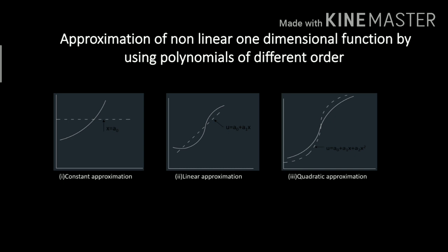But in the case of the third figure, as the polynomial selected for the formulation of the shape function is almost correct, the geometry of the two curves is nearly the same. From that, we can infer that a suitable polynomial is to be selected for the formulation of the shape function. In order to optimize the correct terms and the order of the polynomial, we mainly select the polynomial based on various levels in Pascal's triangle, which we will be discussing in the following slides.